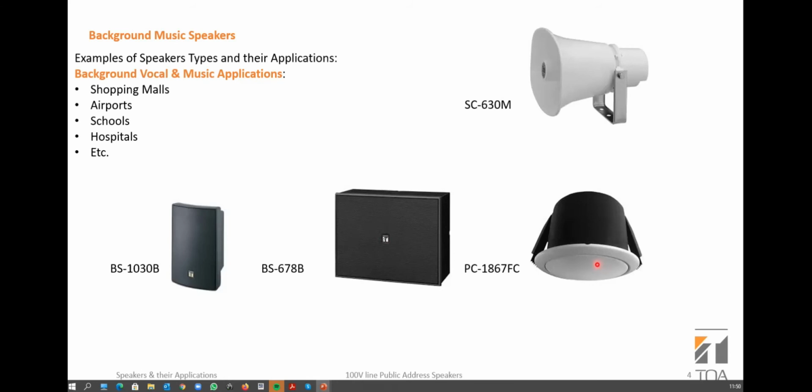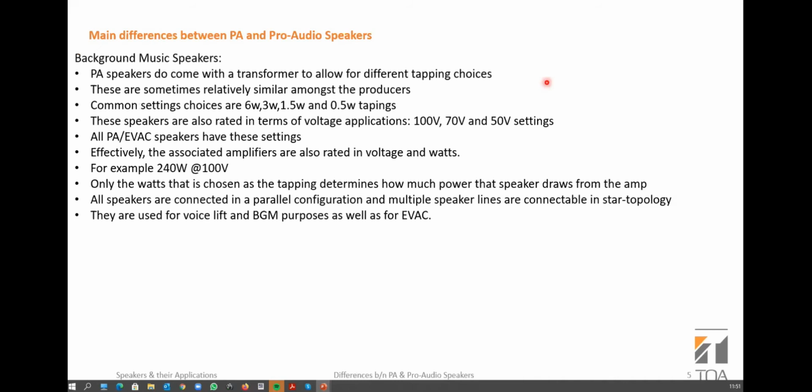So it is very important that if you are doing an installation at a mall, or somebody has approached you to say, come and design my sound for the mall, you need to be careful to ask them, are you going to be playing music? Yes or no? Are you going to do voice lift just for microphones? Do you want to play messages? So we can give you the right speakers that will deliver. It's critical. So these are basically for background music and voice lift. As I've told you, don't play music into the normal standard horn speaker. We do have what we call musical horn speakers that have a lot of frequency response that can play music through them.